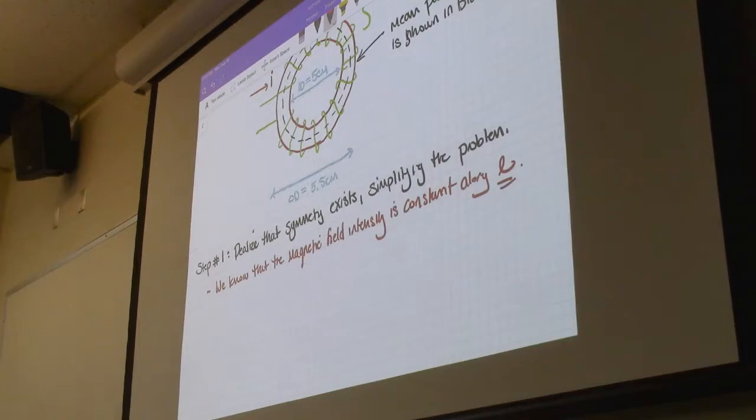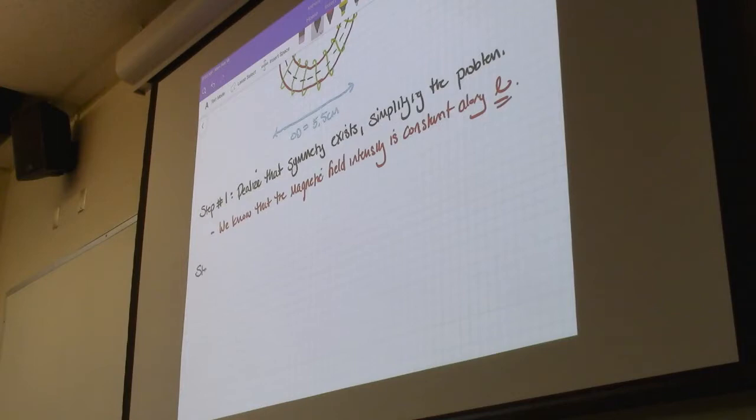All right. Next step. There's a couple of intermediate values that we need in order to calculate H. Step 2 is going to be to find the mean radius. And so that's going to be 1/2 the outer diameter minus the inner diameter.